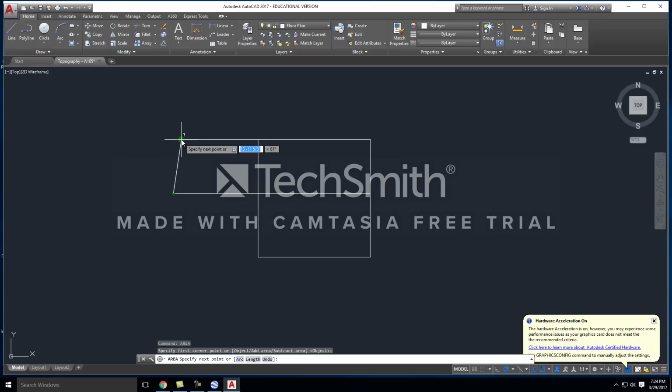What I'm then going to do is specify each of the corners in the space that I'm trying to calculate. As soon as you see the green area fill up the entire space, all you do is hit enter, and you'll notice right here that it says that space is 295.233 square feet. So that's a quick way to calculate the area of your different spaces. As you're creating them, use the area tool to get an idea of how big your spaces are.